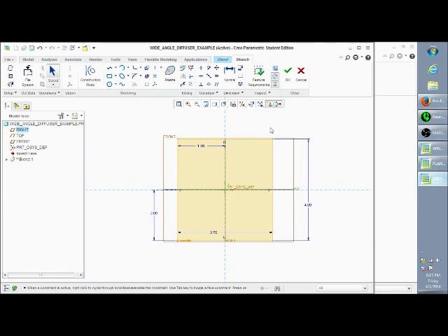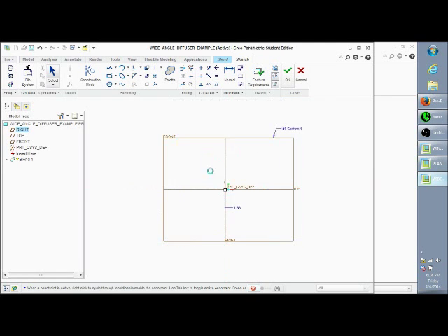So when you go in to create other sketches for your protrusion, you want to keep note of what your starting line is for your first shape, because this is very important, and I will show you how it is very easy to screw this up and not create the shape that you want because of this.